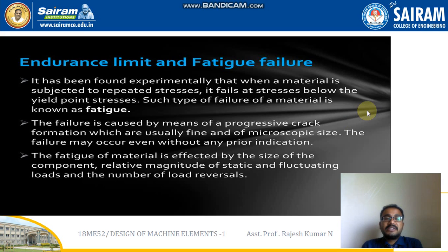Now we have another interesting topic, that is endurance limit and fatigue failure. It has been found experimentally that when a material is subjected to repeated stresses, it fails at stresses below the yield point stresses. Such a type of failure of material is what we call fatigue. The failure is caused by progressive crack formation, which is usually fine and of microscopic size. It means the crack is not visible; only through a microscope can we view the crack. The failure may occur even without any prior indication, suddenly, as this crack may appear.